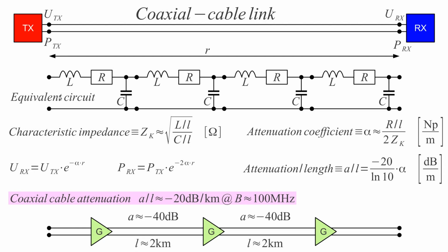The equivalent circuit of a transmission line has distributed inductivity of the inductors, distributed capacitance of the line, and an equivalent circuit should contain many such sections, where we have inductors, capacitors, and resistors for the losses inside the inductors.